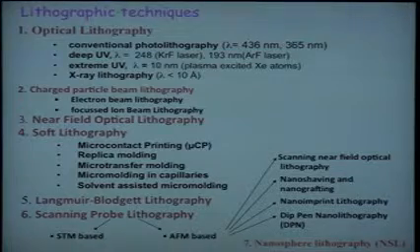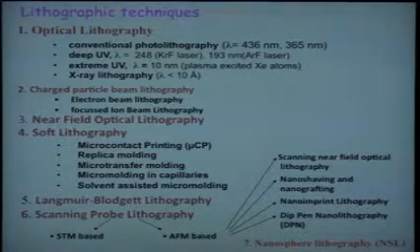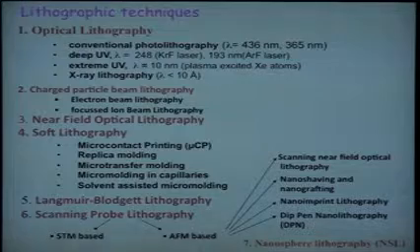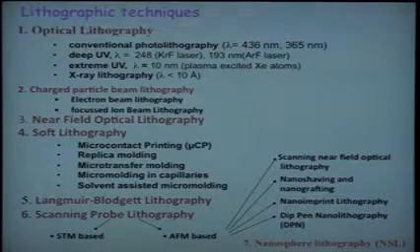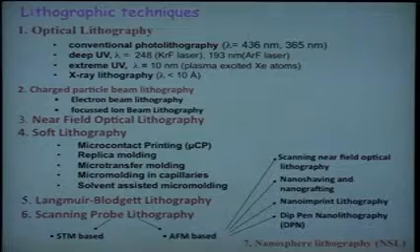So there are different types of lithography methods. Optical lithography, which obviously makes use of light beam, and then charged particle beam lithography, electrons or ions, and again here we have optical, but in a different sense. Soft lithography makes use of stamps. Then these are some air-water interface techniques. Then of course scanning probe lithography techniques. Let me spend a minute or two detailing each one of them.